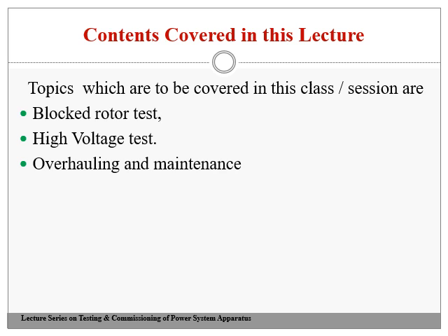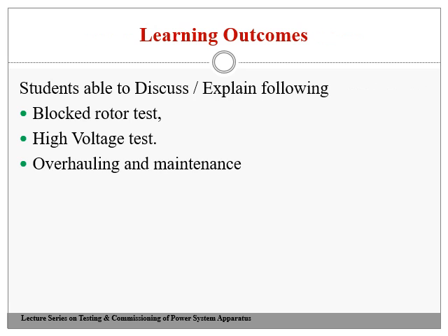It is always essential to check the ability of insulation, whether it can withstand the applied voltage under the high voltage test as per the standard. Then afterwards, it is essential to have proper maintenance and proper operational activities for an induction motor. That's why overhauling as well as maintenance comes into the picture. We'll go one by one.